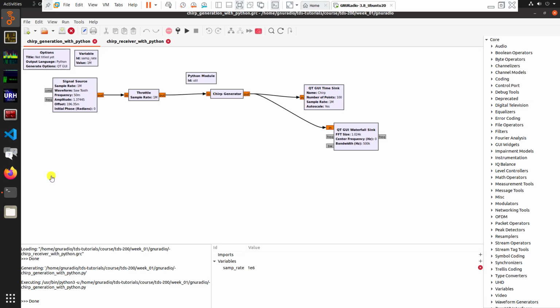The first was to generate this diagonal line of increasing angle steps, the steps from 0 to 360 degrees, and the larger the step, the higher the frequency. And that's going to be done with this block right here. And then we needed to sum those steps together to figure out what our actual angular position is in the sine wave, and that's being done right here.